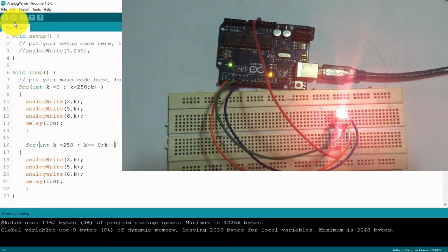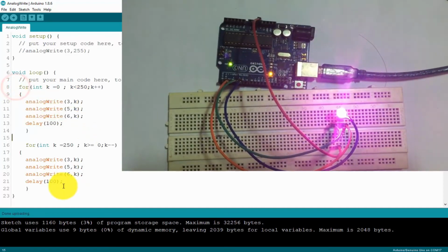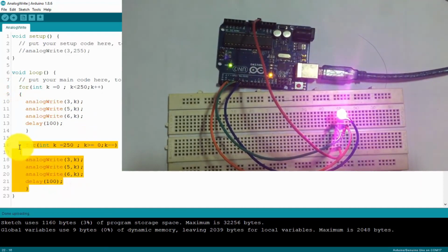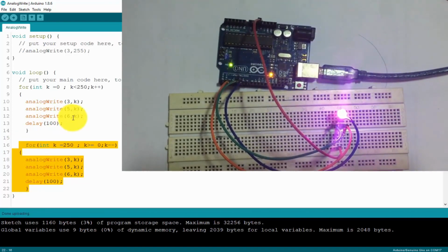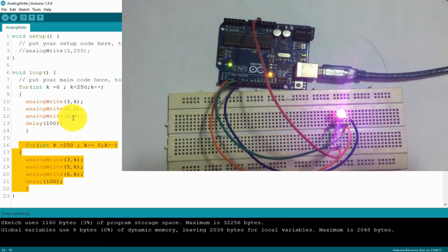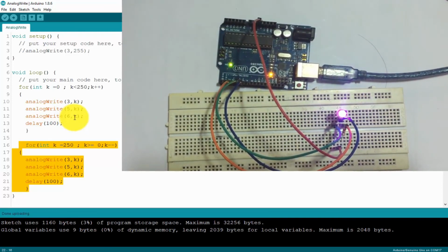Yeah. Okay, you see, you can control LED by this way. Okay, this is the reason why I can control the RGB LED to what color I want, if you know the color table of the RGB. Okay, thank you. This is a useful application you can do with analogWrite.